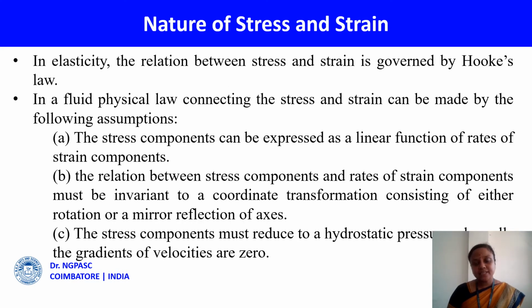So now let us see the nature of stress and strain. In elasticity, the relation between stress and strain is governed by Hooke's law, which states that the strain within the material is proportional to the stress applied, within the elastic limit. In a fluid, the physical law connecting stress and strain can be made by the following assumptions. The stress components can be expressed as linear functions of rates of strain components.